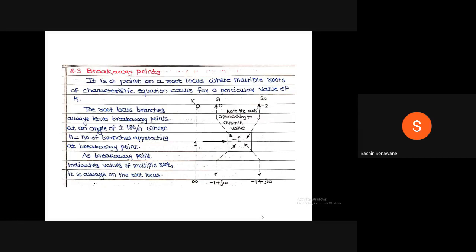First of all, one small leaf is coming from the main trunk, or one branch is there, a major branch. Small leaf is coming and then afterwards it grows and it becomes a branch. Therefore, branch means the point where the root locus leaves or starts or comes out from the real axis or x axis.